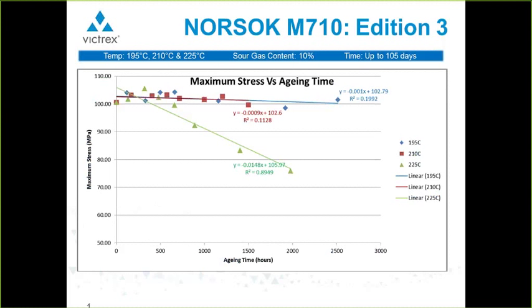So here is the evolution of stress at break over the period of aging. And you'll see that although the correlations are still quite low at the lower temperatures, you do have more measurable change occurring. You can see something happening which tells you that actually the properties are beginning to fall. There is still something of a muddle in this first few hundred hours of testing where you have different processes occurring in the polymer, and I'll come back to that in just a moment.